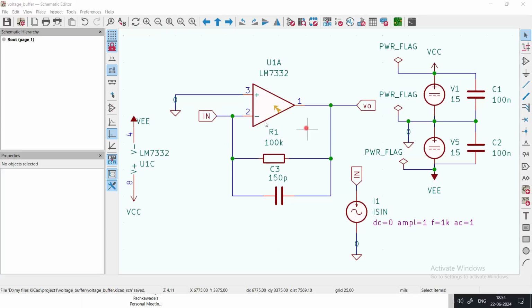You would like to design this circuit in such a way that it can cover a wide range of input current range to convert satisfactorily, with a constant gain and large bandwidth of the signal frequency, and provides you output accordingly. So you can choose a part, not necessarily this part, but as per your requirement. So obviously I need not model, add the spice model of this part. I have done that because I'm doing a real world design and simulating the performance of a real world circuit.